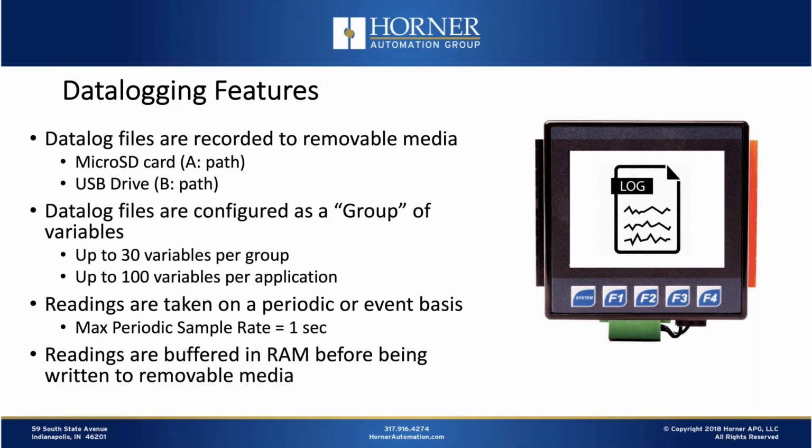Now, data log files are configured as a group of variables. So a system designer would decide, okay, I've got this group of variables that I want to log or record the values of, and I want to group these together. And you can have up to 30 variables in a single group, which would then be logged to a single file, and up to 100 variables per application. And we're looking at increasing those numbers in the future, and we'll talk about that later.